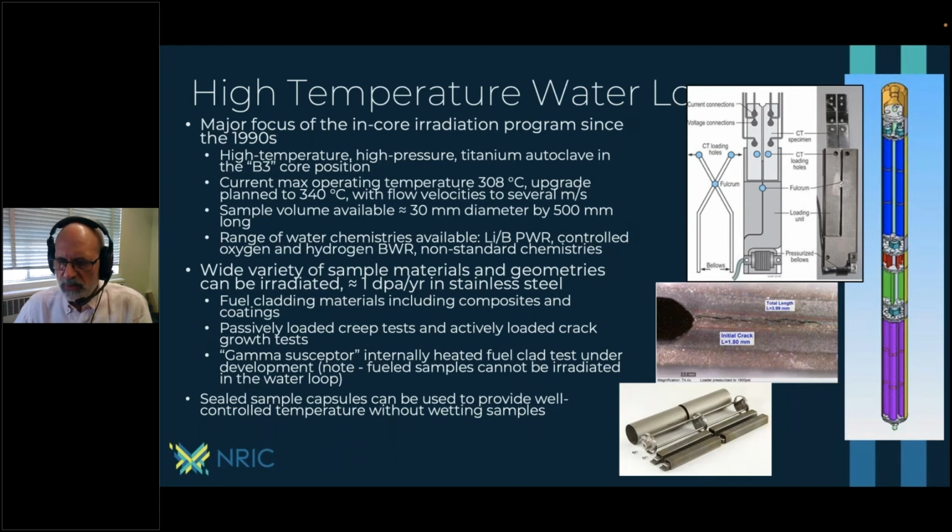Basically you use a high pressure bellows and the loading assembly that you see there to apply controlled, usually cyclic loading to a crack, and you can measure the crack growth in situ by measuring the potential drop across the sample. Then the bottom picture shows a creep test facility that we used for measuring creep on silicon carbide composites. And so we tend to emphasize those kinds of experiments in that we aren't generally testing fuel, certainly not in the water loop.